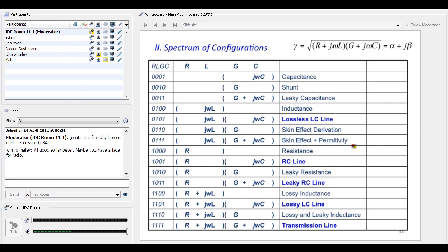What is he talking about? Well, once again, here's the guiding equation for a leaky feeder, actually for any coax cable. And you have terms, the resistance of the cable, this thing called inductance and capacitance of the cable. Those factors come into play, and you got modules that are going to highlight this. So if you're an EE or a Chem-E and you're not used to this electrical engineering, this physics stuff, don't worry about it. You got great people that are just pointing out the terms. I could change the material, different materials, plastic, rubber, types of plastic have different values of capacitance and inductance, and resistance tends to be the wire itself.